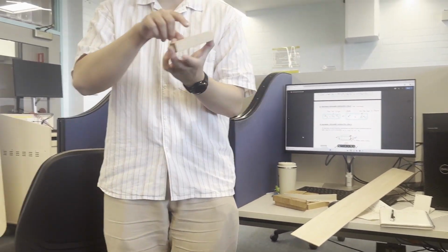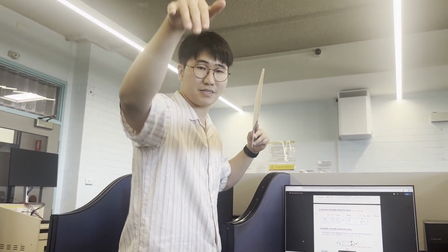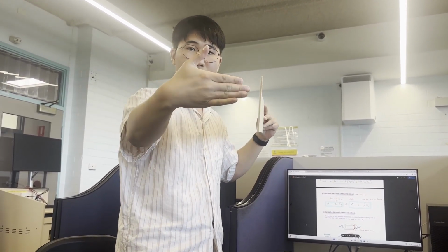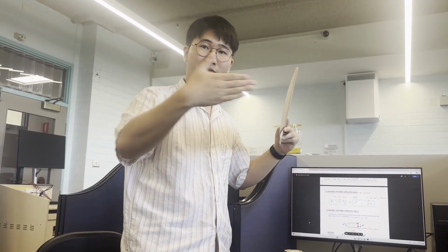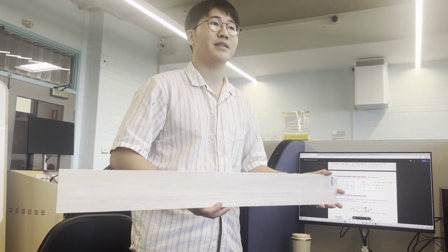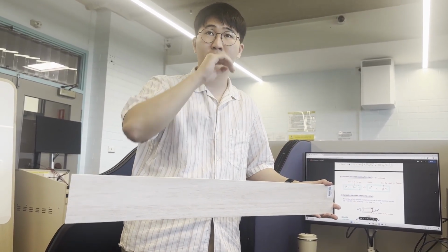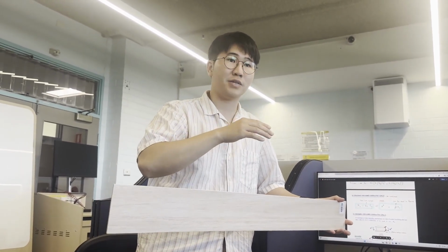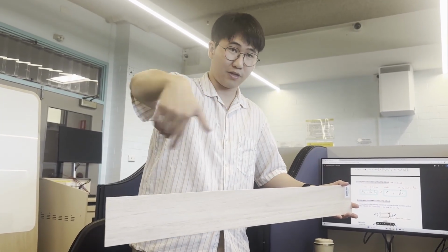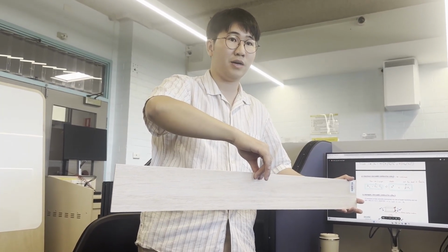Lateral torsional buckling won't happen for a shape that's more balanced like that. It's just for shapes which have a large difference in their bending stiffness that way versus that way. Because that way, it's going to want to bow out, right? But this is what happens with I-beams all the time, okay? And what you'll find is that there's things later that you find out about called full restraints, partial restraints, and lateral restraints, which are basically, do you remember how the top is bowing out? It's basically like pinching the top, so it can't bow out in compression.